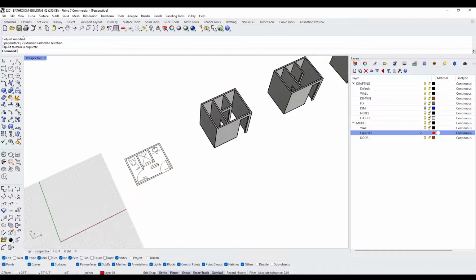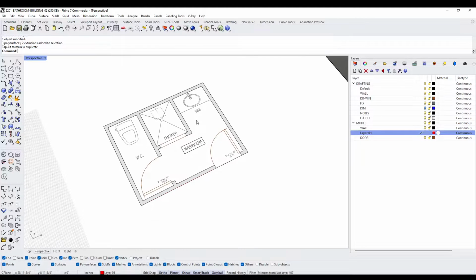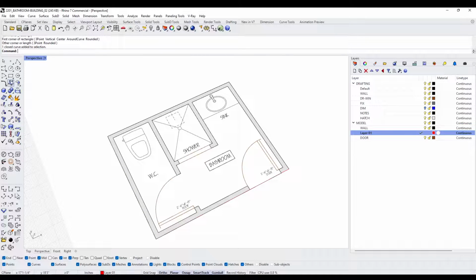So let's move this over. And I feel like this one you guys will like, because I feel like this is actually one of the cleanest ways to do it. So we have the outside line, which I think we already have here in red. Then we want to do this inside portion. So the spaces are going to get a polyline. So I'll go to polyline from here, here, and work my way around this space. Then C to close. And then I'll do this one. So now we've created basically the perimeter for all of the walls.